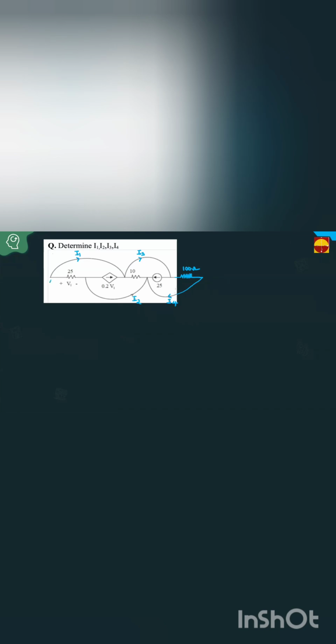Now see, let this node be A, this node B, this node C, this node D, this node E, and this node F. What is the observation here, friends? A to C, C to E is connected through one wire only. A, C, E are common nodes because they are connected with one wire. I told you already, if it is connected with one wire, it is taken as one node. Similarly B to D, D to F is connected with one wire only. That is one node only.